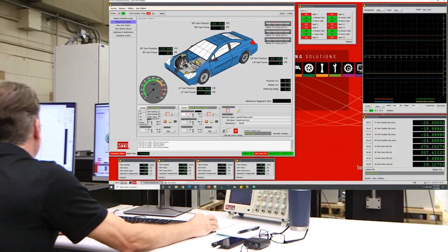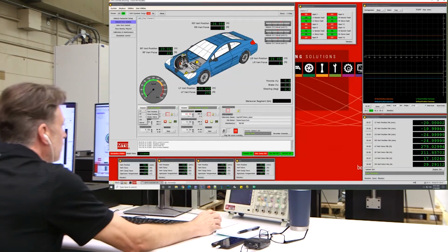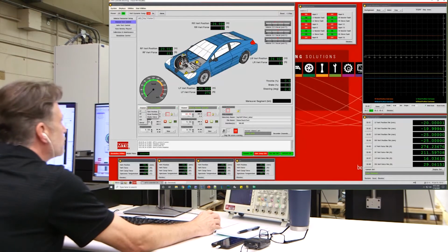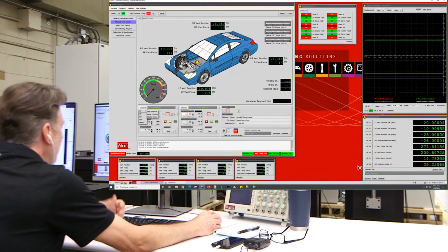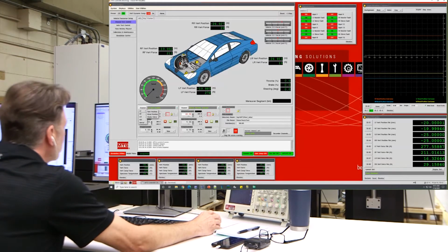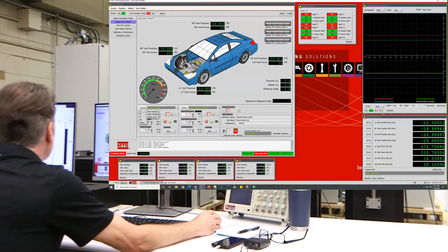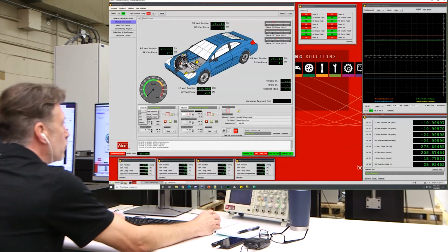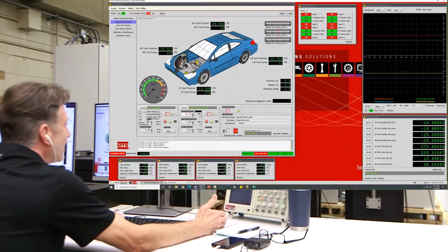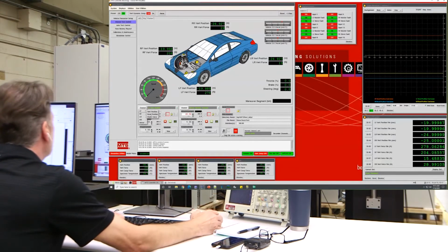We've got down here, I'm going to move to the static force that was also presented by Ford, the static force to allow us to handle the base force provided by a spring. We don't want to use all of our energy in these permanent magnet motors to hold a high static force, so we take advantage of this pneumatic channel. And then there's a road position. The road position is actually a virtual channel. This gives us the ability to drive at the contact patch of the simulation a vertical input. We're going to be demonstrating this in just a moment.